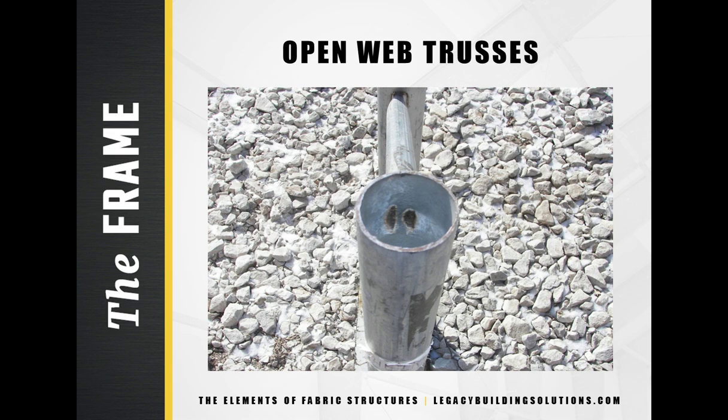Hollow tubes pose a serious durability issue in applications where the buildings are exposed to corrosive conditions. Corrosion can originate inside the tube, out of sight and undetected, and corrode the frames from the inside out. Once corrosion begins, it can worsen quickly, and often the damage is irreparable.